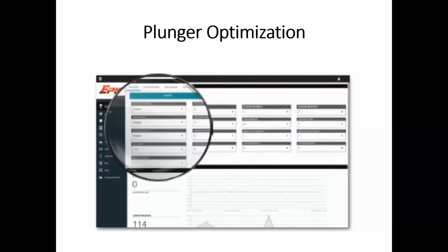Bypass plungers can change this calculation because they're falling against flow and typically making round trips during the lifting time. So we may see double sometimes, depending on the rates and what it's falling against, on the arrival time. Arrival times can highly influence production rates as well as equipment preservation.